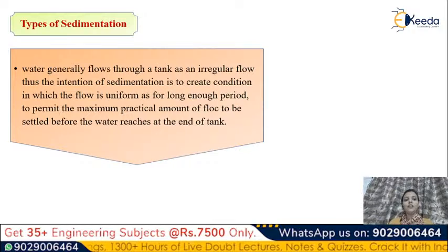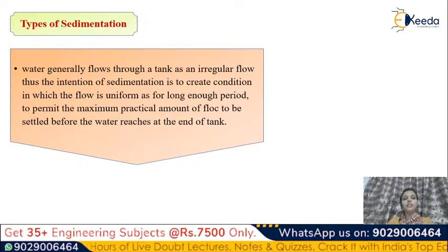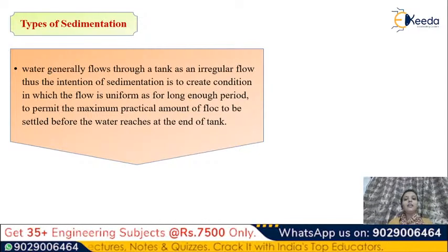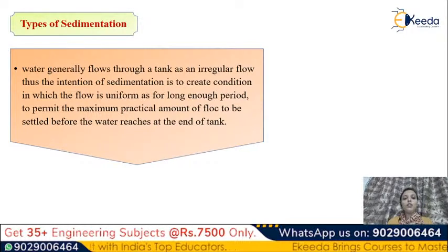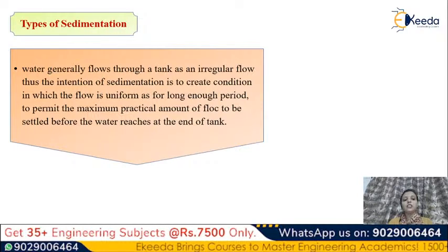Water in a horizontal flow sedimentation basin generally flows through the tank as an irregular flow. Thus, the intention of sedimentation is to create the condition in which the flow is uniform for a long enough period. Basically, we provide a sufficient detention time to permit the maximum amount of particles to settle down at the bottom of the tank.